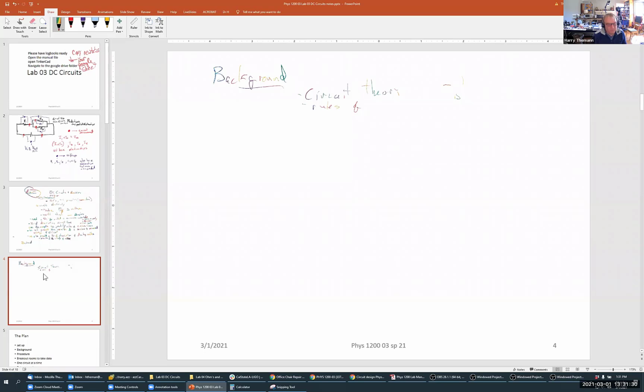Then what else? Oh, this is when you describe the meters. And remember, there is current through, voltage across. This is very, very important. So that means that ideal is our ammeter equals 0 and our voltmeter equals infinity.